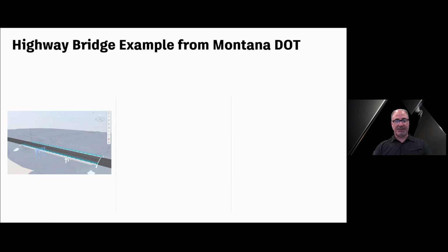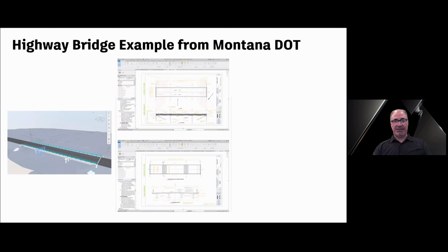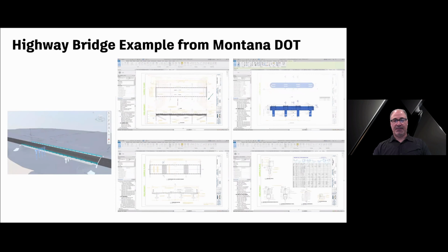And once they get the bridge published into Revit, they are leveraging Revit to add all the rebar details and do all the construction sheets in exactly the way they like to present them and publish them. So this illustrates how you can go from the parametric InfraWorks model with your own content into Revit with full documentation. So this is for your highway type of bridge.